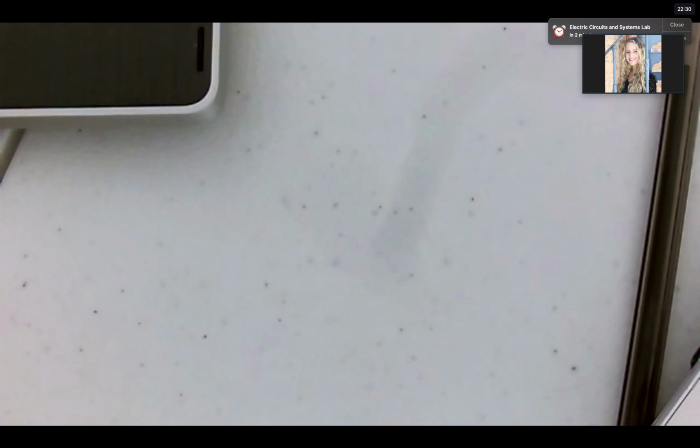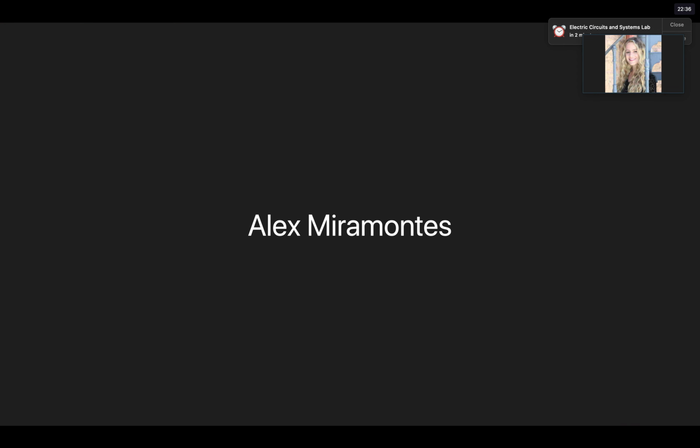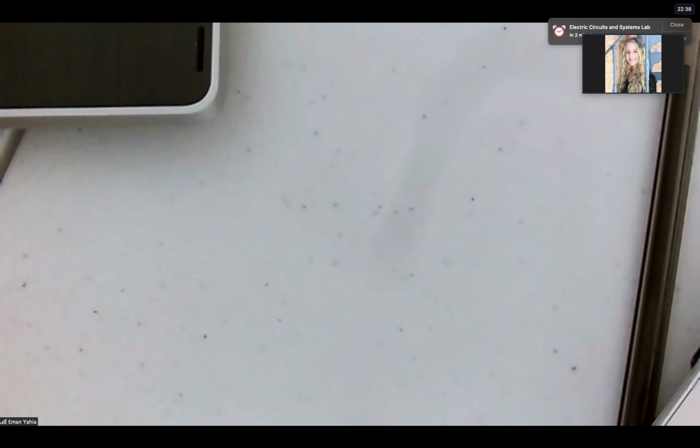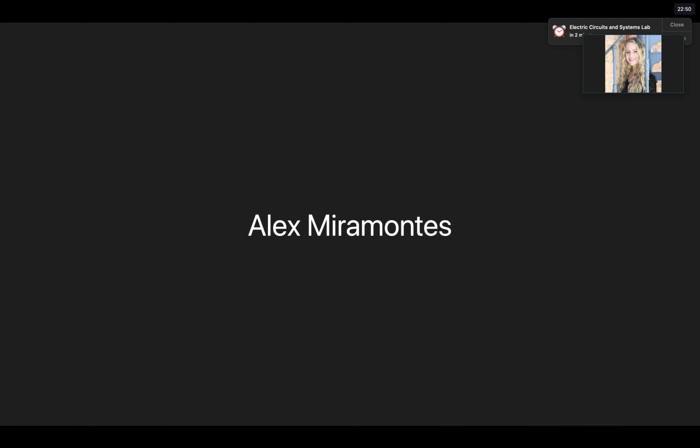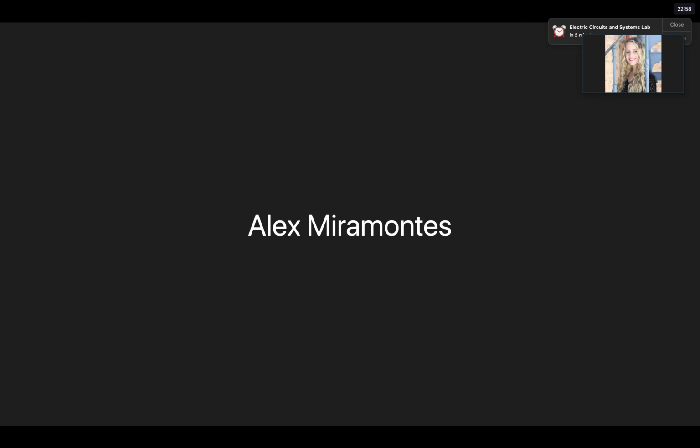That means maybe you need to make the run longer, or you made some mistake in the output, like you chose the dynamic pressure instead of the static or the average pressure. So just go ahead and see what you can get. Okay, thank you. But it looks good. The pressure and streamlines, first, the physics is correct. Okay, thank you. You're welcome.